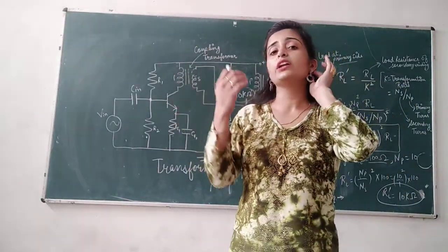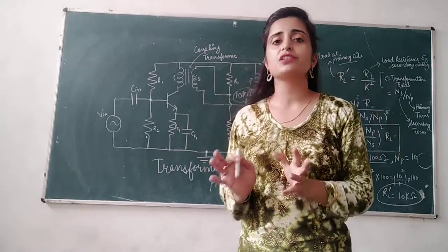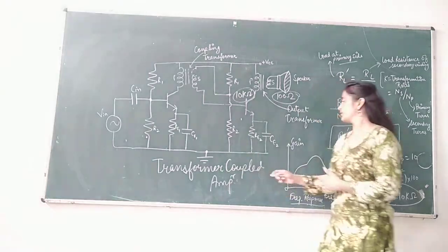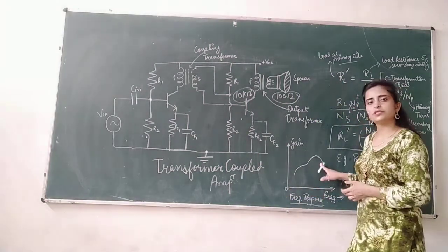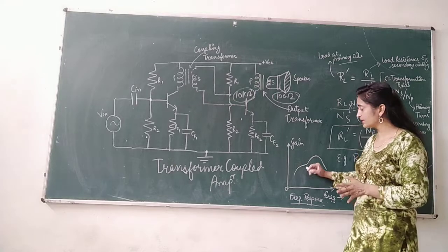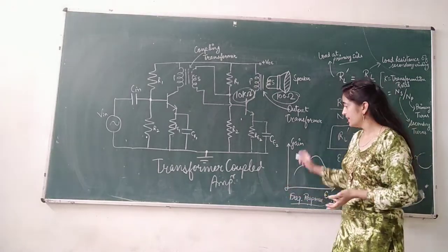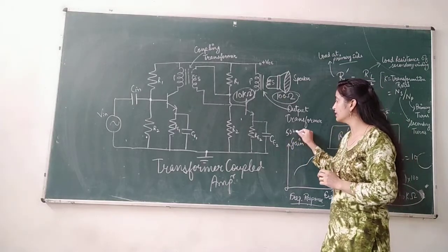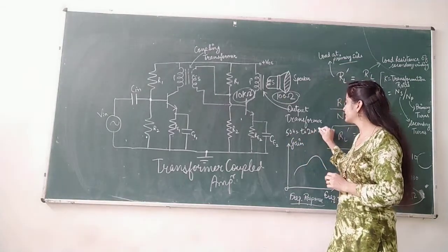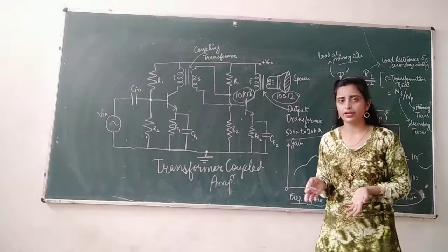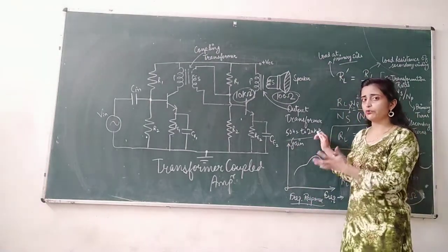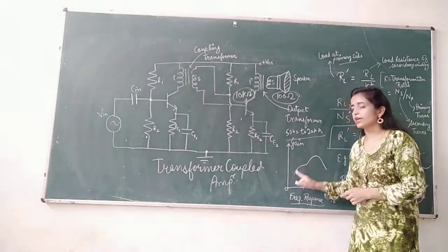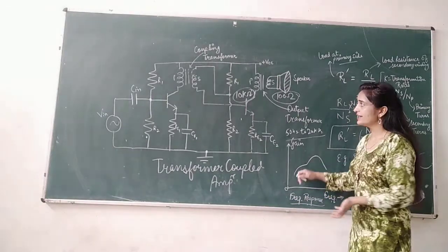But when we talk about the frequency response, it is not that good. If you look at the frequency response in the audio range, that is 50 hertz to 20 kilohertz, at low frequencies the gain is falling down. Why is it falling down?